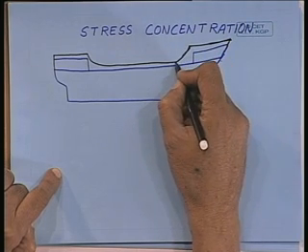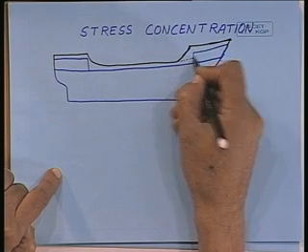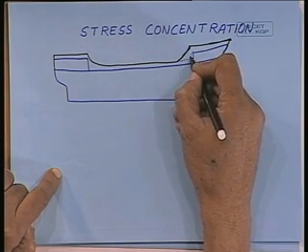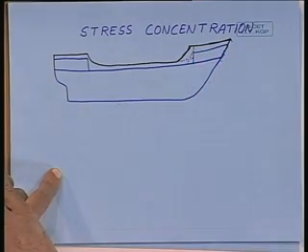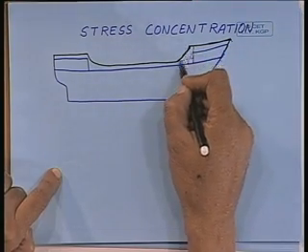Now, if we wanted to give the bulwark, we could have finished it here, put a ladder sort of a thing here, and then start the bulwark and then finish it. But we don't do that. There must be some reason why we are not doing that. Can you tell me what the reasons are? First of all, a continuous member will take the load for this break. Part of that load comes later on.